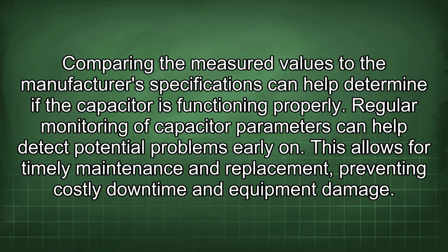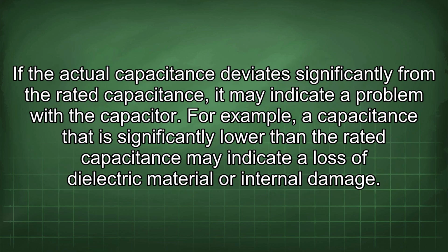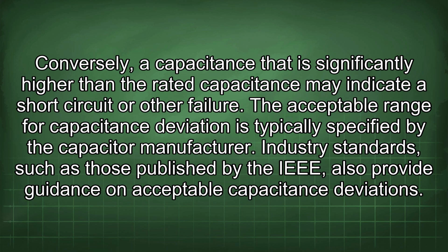This allows for timely maintenance and replacement, preventing costly downtime and equipment damage. If the actual capacitance deviates significantly from the rated capacitance, it may indicate a problem with the capacitor. For example, a capacitance that is significantly lower than the rated capacitance may indicate a loss of dielectric material or internal damage. Conversely, a capacitance that is significantly higher than the rated capacitance may indicate a short circuit or other